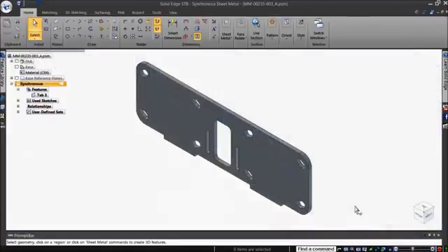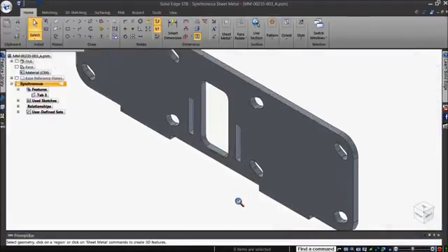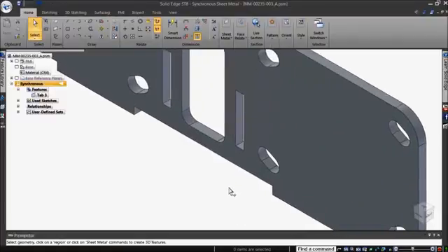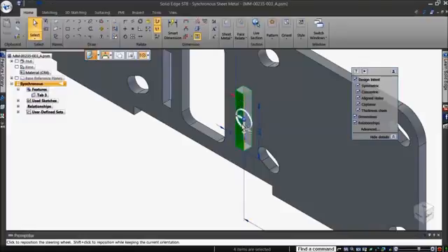Finally, this is how the steering wheel is used to move the geometry to a set distance from other geometry or from a reference point. First, the steering wheel is indexed to set distance from the face being moved. Then shift-click the axis and key in 12 millimeters. Click once to set the offset distance.